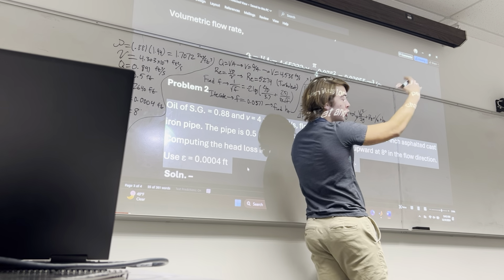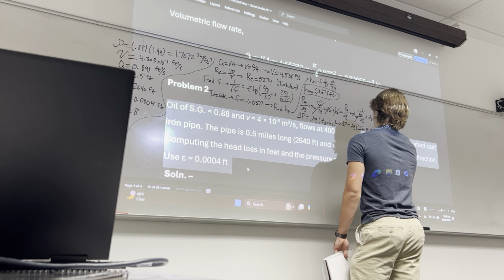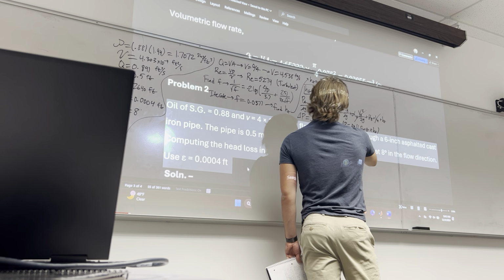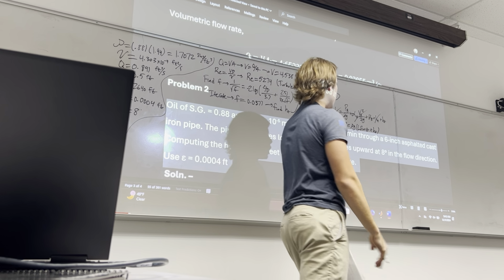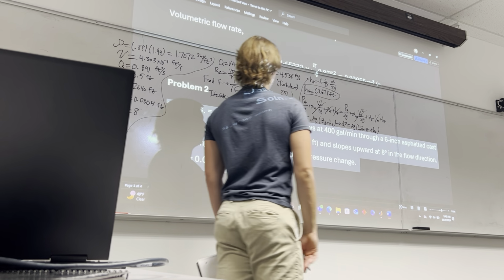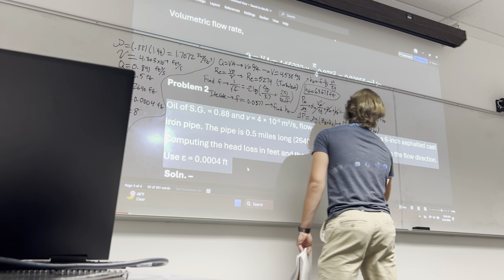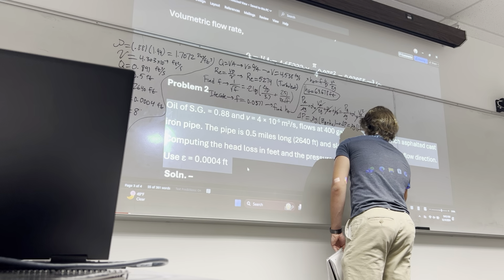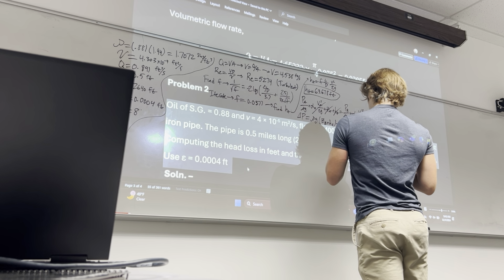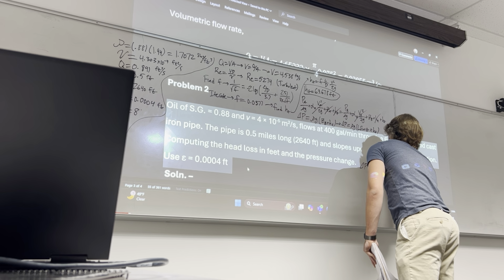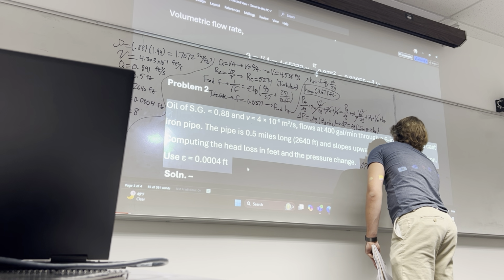It's just trigonometry, plus HF. We know HF, we know theta, we know L, we know rho, we know G. So go plug in all the numbers. You're basically done at this point. We get delta P equals 23,698 PSF, pounds per square foot.